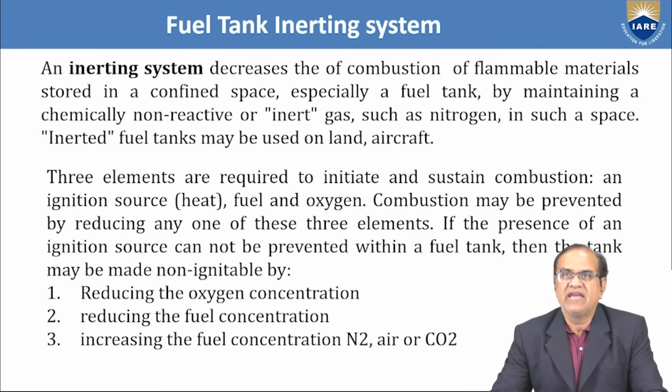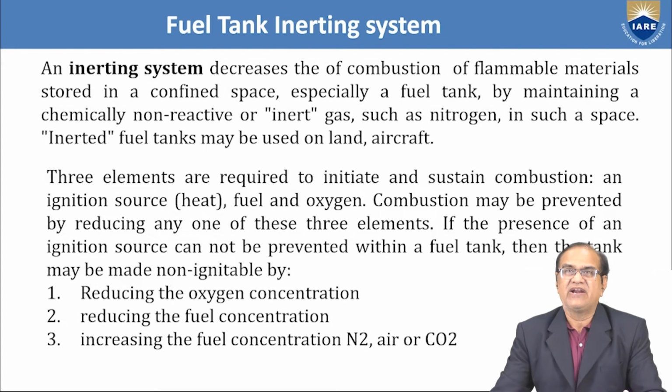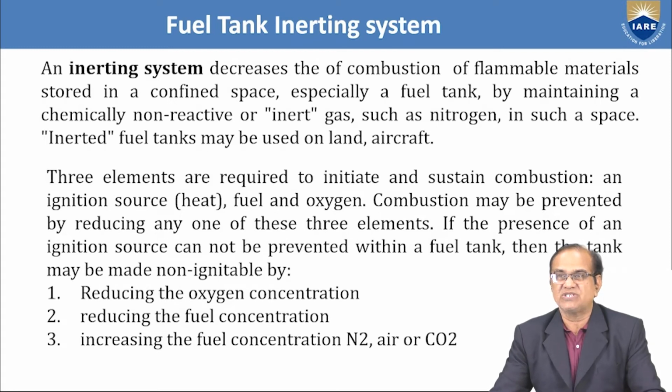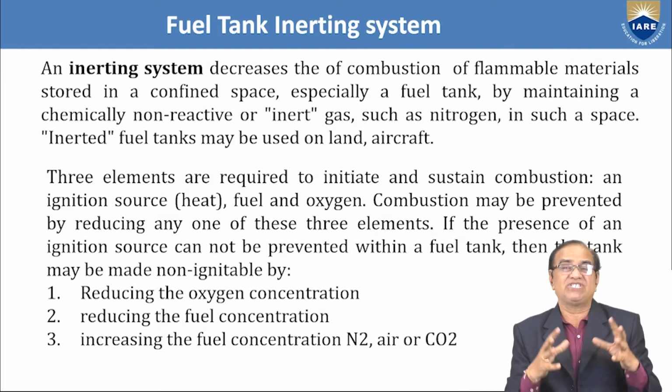Fuel tank inerting system. Inerting means we are making sure that this is not going to catch fire. An inerting system decreases the combustion or flammable material stored in a confined space, especially a fuel tank, by maintaining a chemically non-reactive or inert gas such as nitrogen in such a space. An inerted fuel tank may be used on land or aircraft. So we use some special type of gas, which is inert gas.